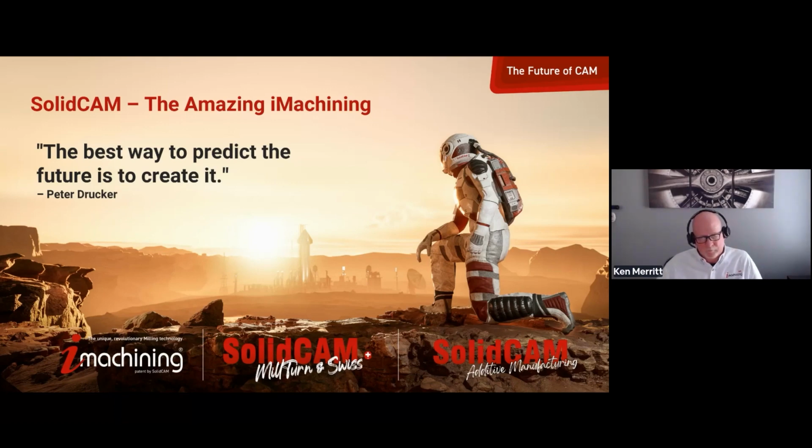All right. How does the usability compare to MasterCam? That's a kind of a personal question for different people. Everybody has their own ideas on usability. One of the things that I really like about the way we do it is that we do a lot of the calculation for you. So instead of having to figure out what step over and what feed and speed I'm going to run at and why relative to the material, all I really need to do in using iMachining is simply input to the material database what the ultimate tensile strength is and its machinability factor.